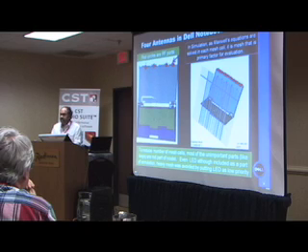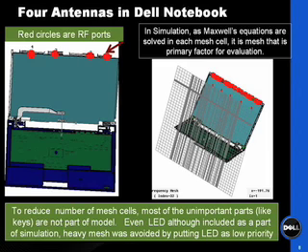So one thing I liked in CST is you can put all the components. You don't have to actually eliminate all the components. The way to do it is there is a priority, so you can prioritize the meshes. Some components which are secondary, like keyboards, all the keypads and all the things on the bottom, you can put secondary priority. And the antennas, magnesium frame, and the flex, you can put all as primary. This way you can solve your antennas in the presence of all other things.